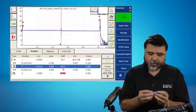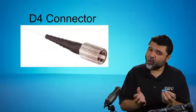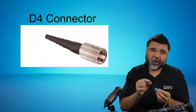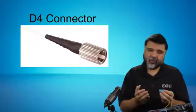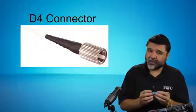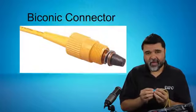And so there are some older connectors in the system. You might have an old D4 connector, which is a 2.0, a 2 millimeter ferrule. It's an older connector that typically has higher reflection. And so if you're expecting to get minus 45 dB out of an old style connector like a D4 or, even worse, a biconic, you're probably not going to get it.